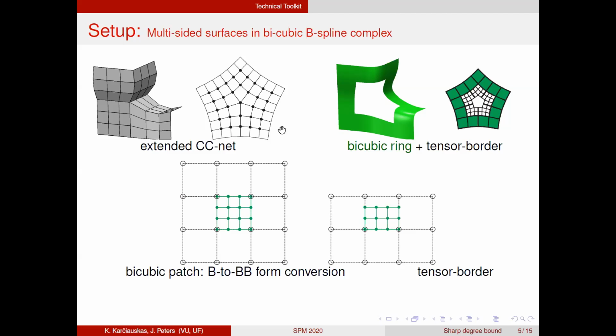And the places where we do not have the next layer, because we have an extraordinary point and we go beyond, at this point, at least we can convert 12 B-spline control points into 12 Bezier control points. And these extra Bezier control points that we see here, we can look at as being along a border or boundary, as being the Hermite extension up to 2nd order into, well, into this piece here now.